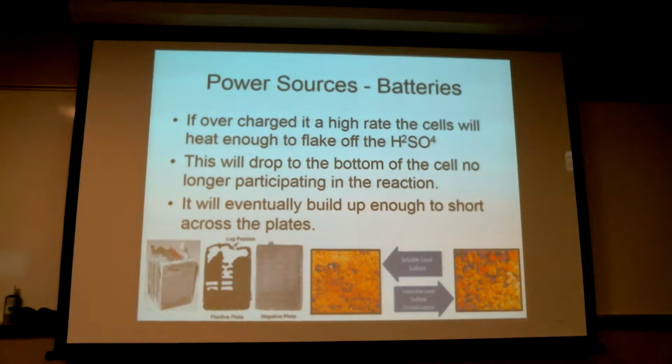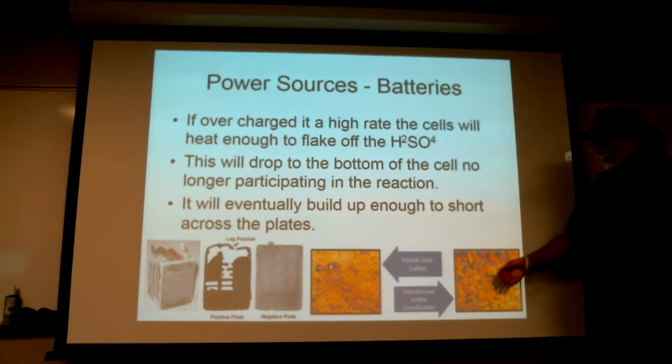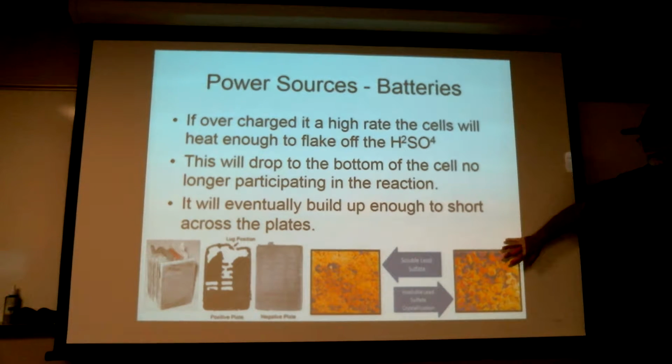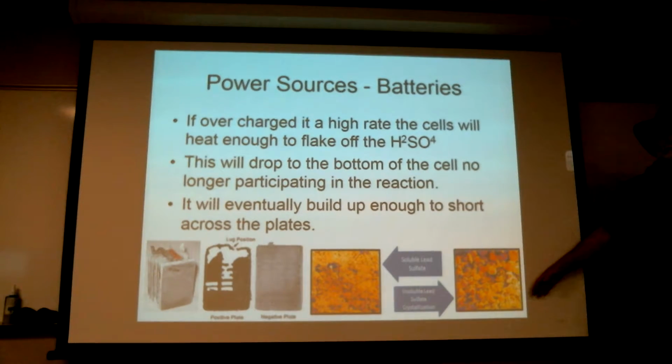Now, in the last, I'm going to say 10 to 15 years, some folks have figured out that if you take the battery, particularly one that's kind of old and needed some loving, and instead of putting it on a nice constant continuous charge, you hit it with about 40 amps for about 1,000th of a second, or maybe 2,000ths of a second, and then stop, wait for a little bit, or go to a very low trickle charge, and then maybe a tenth or so of a second later, do it again, and you keep what's called burping the battery, that tends to help cause these nodules to break up and dissolve back into solution. It's called burp charging.